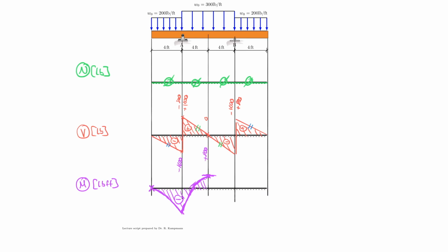And probably the easiest to start with is right here, because you know it must be 0 there. And then I think the easiest thing is to follow this slope. I'm 0 here, and then I'm getting negative in my slope, right? 0, negative, negative. And then here I have a positive slope, and it goes from a lot positive to less positive. So therefore, it's actually a mirror image of what I already have here. So I just need to mirror that over and draw my belly shape here to negative 1600. And then I copy the other side, which was a little bit flatter.